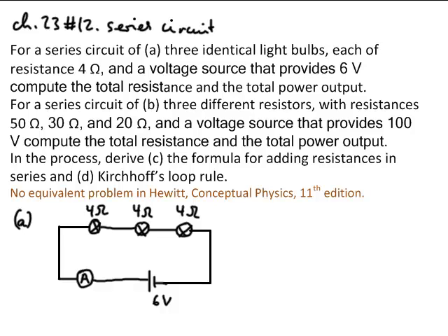Okay. Actually, I will turn to the book here, which says on series circuits, among other things, that electric current has only a single pathway through the circuit. This means that the current passing through the resistance of each electrical device along the pathway is the same. That means the 0.5 amps that we saw is running through any one of those resistors. I will go back in a little while and show you that in the simulation.